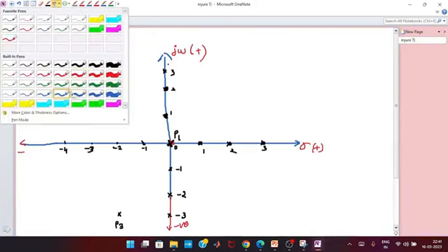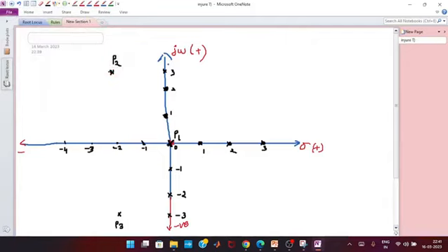and the left side, right? So on the left side of the particular pole, consider how many poles are at the right-hand side of this particular test point, this is test point T. With respect to this point, how many poles are lying on the real axis? If it is an odd number, then a root locus branch exists, right? So tell me where the root locus branch starts and where it ends.